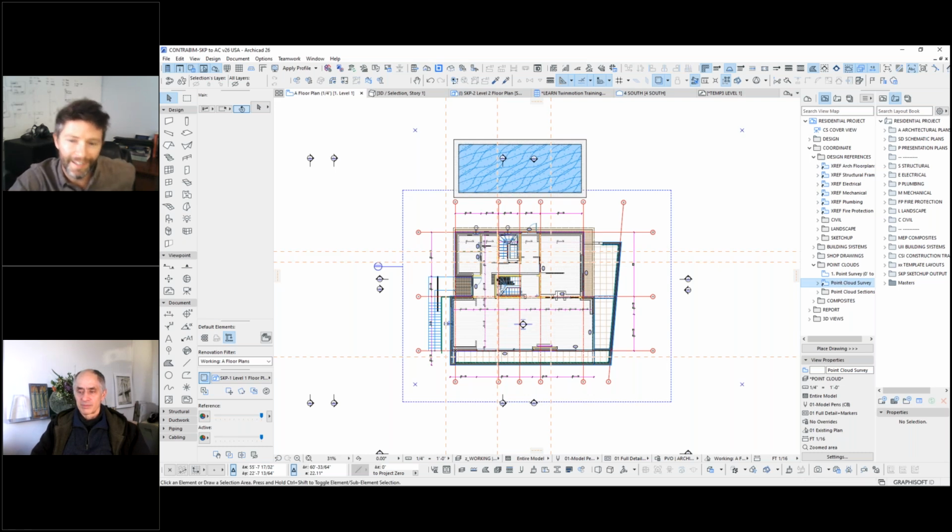No, unfortunately. ArchiCAD still lacks the ability to document points, meaning even if you have a view with the point cloud turned on and you put that view as a drawing onto a layout, you're not going to see any of those points. The only way you can translate points to a layout will be through an image type format, which will pixelize things, but a 3D document will not do points, unfortunately.